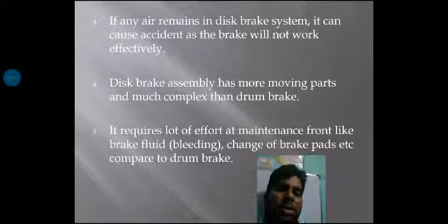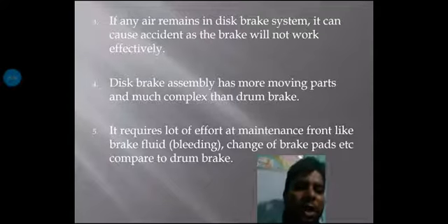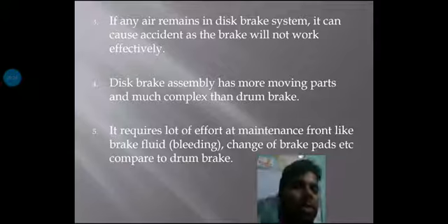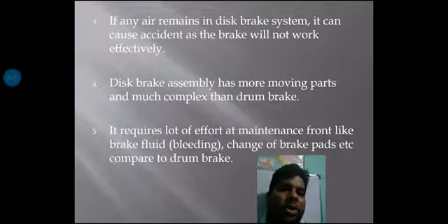But one question is there, how can we calculate that capital P? That P means the total operating force, which is equal to the actuating pressure times the area of the pad. That means how much portion is covered by the pad. Suppose the theta angle portion is covered by the pad, and the intensity of pressure is applied on the pad.